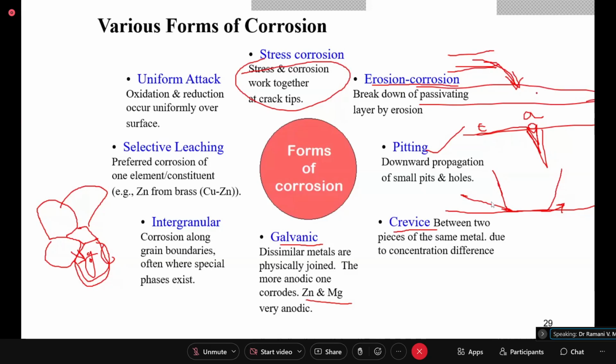When it is cast into a sheet, nucleation starts in a random manner, just like this. The atoms of iron will arrange themselves around each nucleus very nicely. In the same way, it will start solidifying from here and go like this; here it may start from here and go like so. That is why intergranular corrosion happens: it is the grain boundary which is eaten away by caustic soda or another corrosive environment.